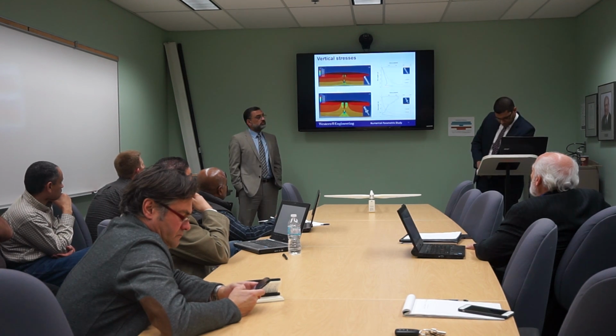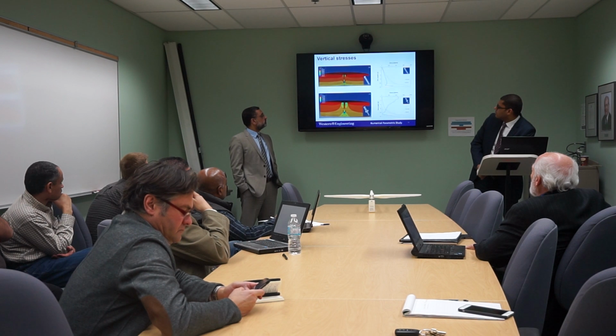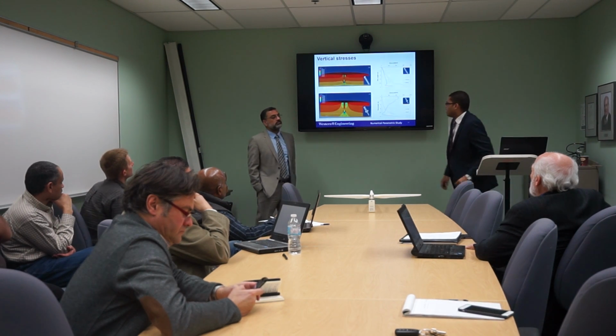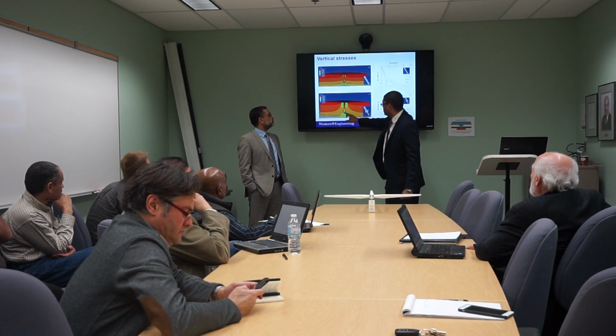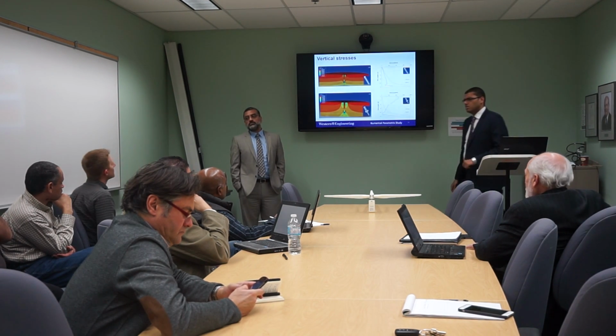So how far down, what's the distance between the bottom of your pile and the bottom of the model? It's that distance, right? This distance in this page was 4 meters, and the total I think 60 meters. Okay, do you think that was enough?